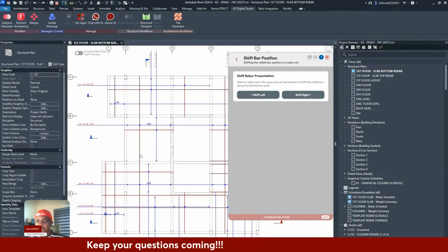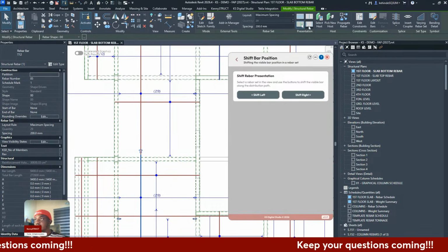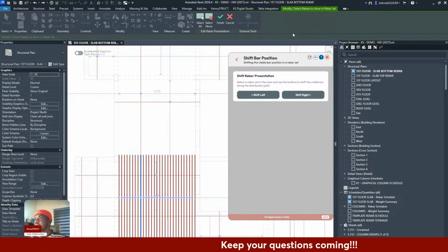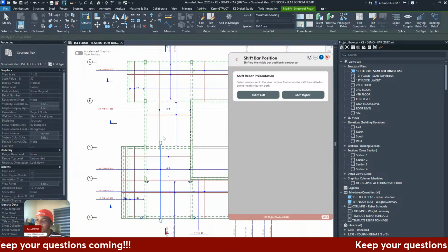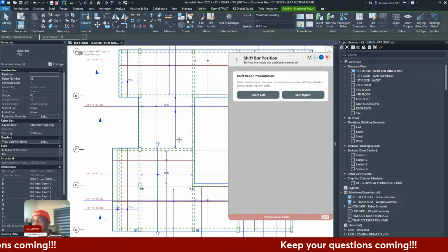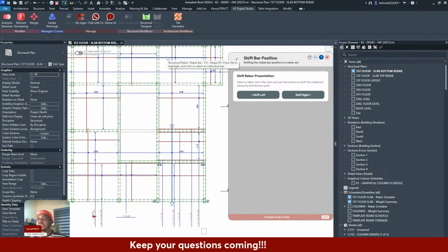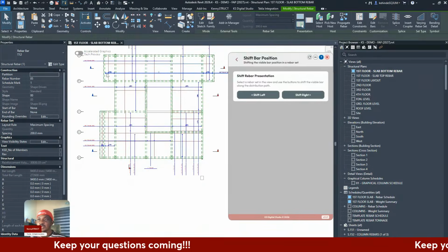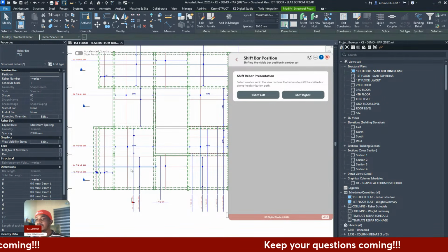Normally, what you would do with the available tools in Revit is click on this, then click on select bars and check this one, then pick the bar you want, then click finish. It's frustrating if you want to do it multiple times. So you can just select multiple bars, the ones that have the situation. That's one way you can find them with your eyes.